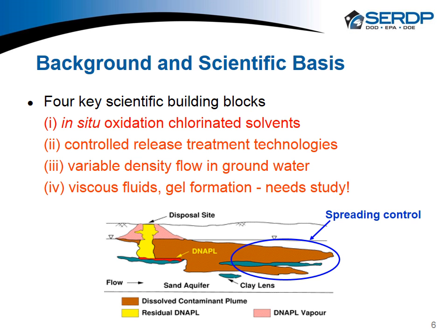So yes, it's an issue that water salinity could be impacted, but I think if we're careful and strategic, we're trying to locally control things. Because we're at the downstream end of the plume, we don't have to overdose with the treatment chemicals, because we're just trying to get enough permanganate in to knock out less than 100 micrograms per liter TCE and so on.